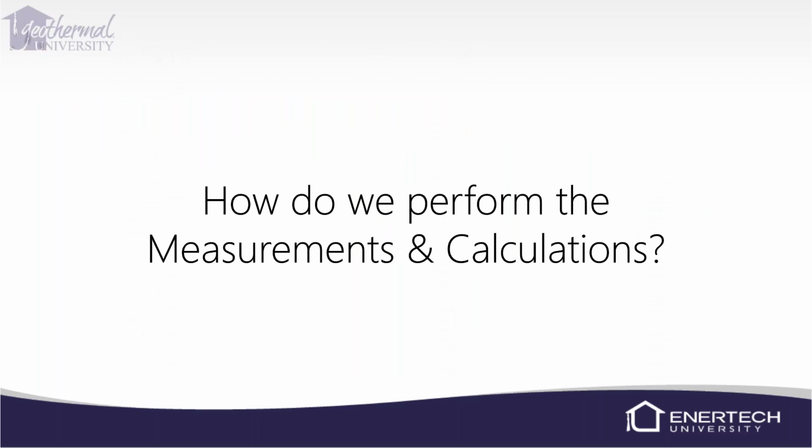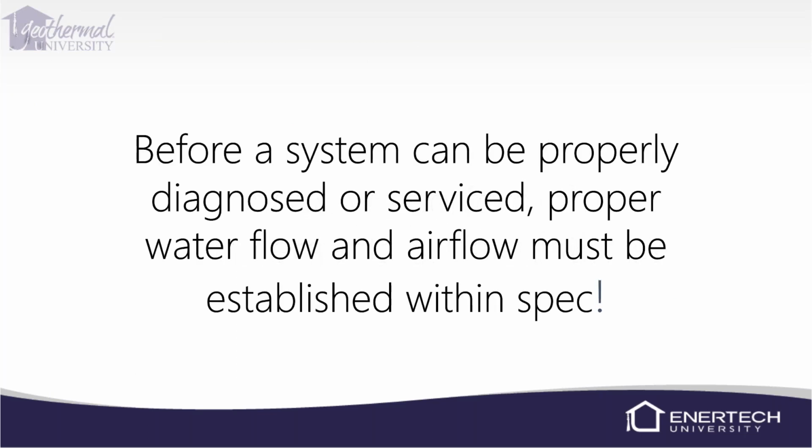So basically, how do we perform the measurements and calculations in order to get what we're pulling out of the loop field? Before the system can be properly serviced or diagnosed, we have to make sure water flow and airflow are established within specs.